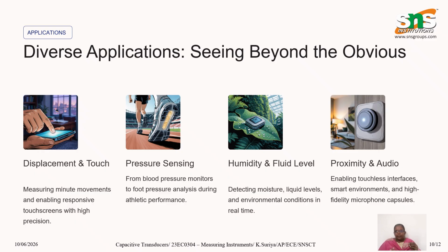Capacitive transducers are widely used in various engineering and industrial applications. They are used for displacement measurement and position sensing in automatic systems. They form the basis of modern touchscreen technology, enabling responsive and accurate touch detection. In medical applications, they are used in pressure sensing devices such as blood pressure monitoring systems. They are also employed in humidity measurement instruments and liquid level detection systems.